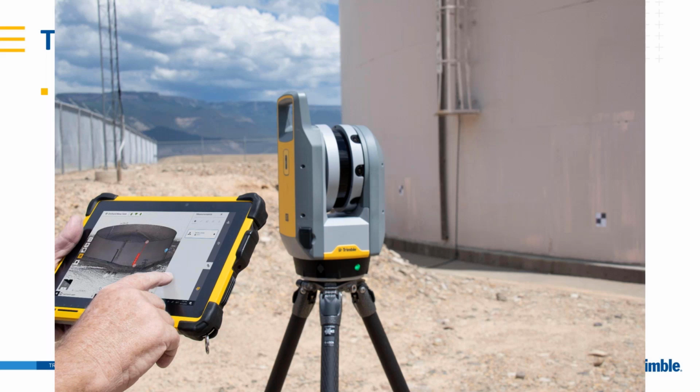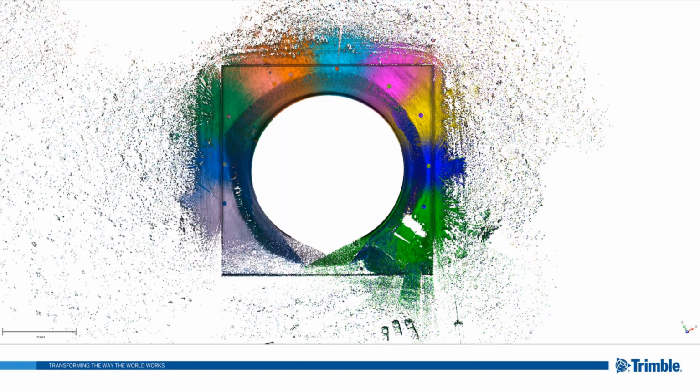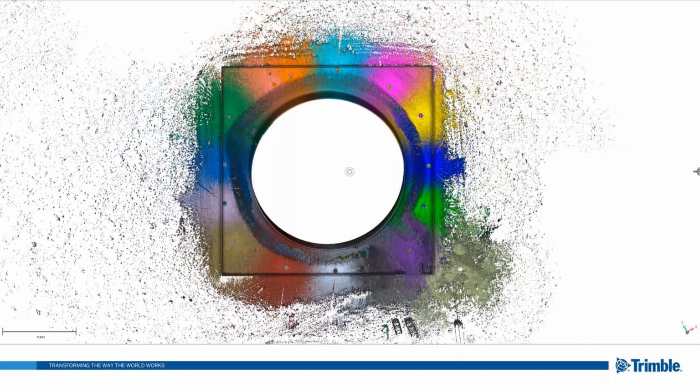And you can put these together either by using the point cloud itself or using targets such as black and white checker targets. You see a couple of these on the tank there. And the way it works is you'll start out by capturing one scan, then the next, then the next, then the next, until they all come together to create a final 3D replica of your tank.